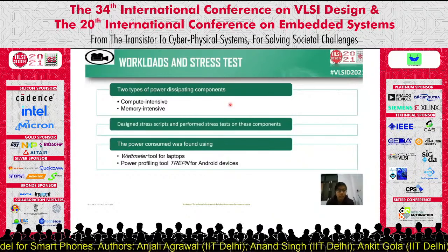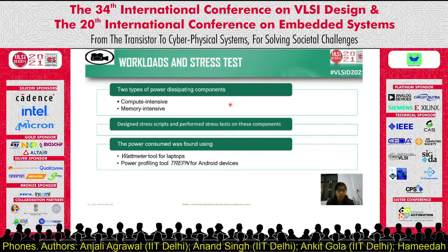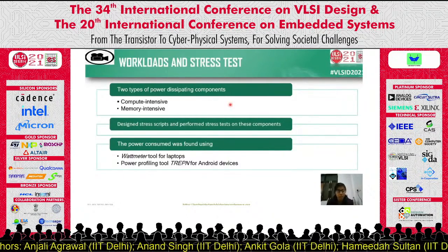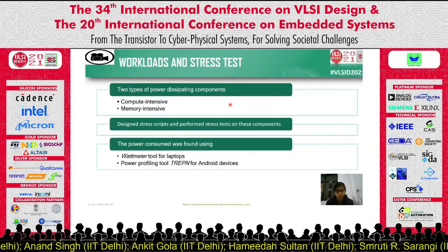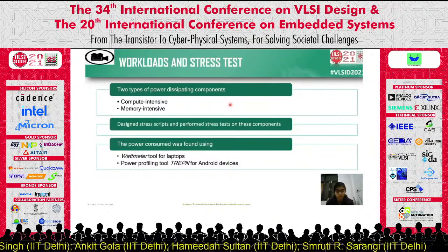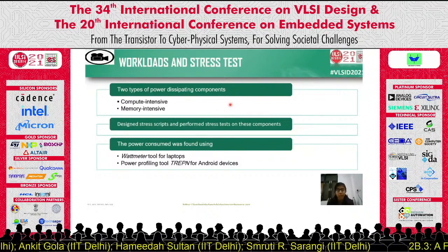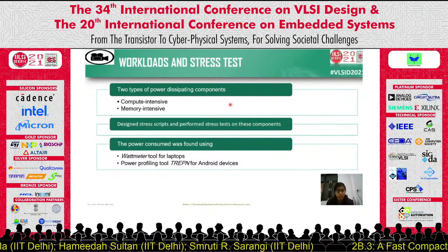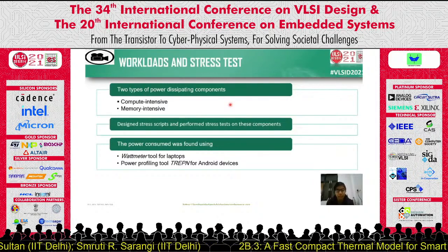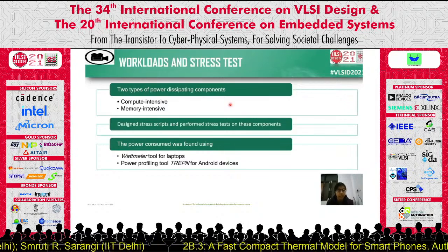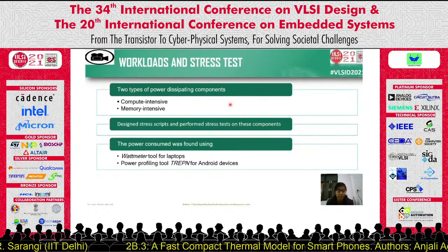During the stress test for the memory, the processor also consumes some power. So to accurately calculate the power consumed by the memory, we first run a program on the processor without adding the memory instructions to it, and then we subtract that power from the results of the memory stress test to obtain the accurate power dissipation value for the memory.